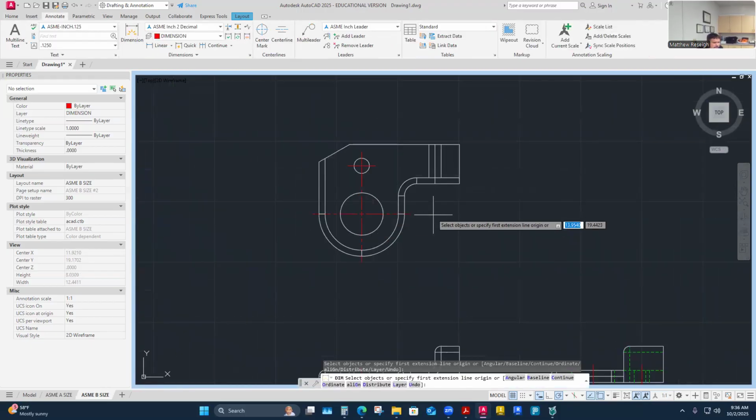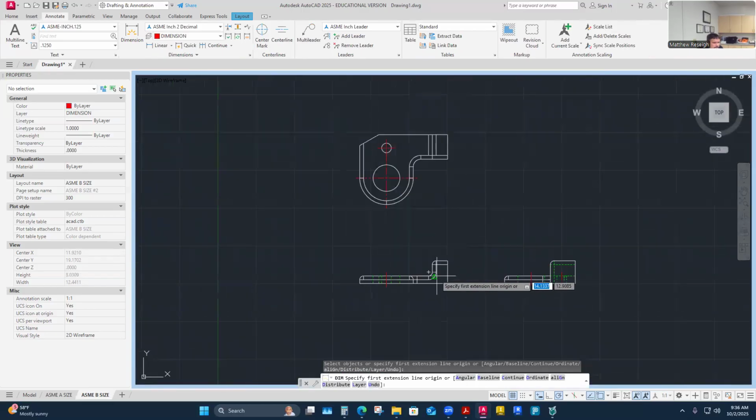So overalls. And really, I'm trying to get your heads working around like I'm going to have what I call these datums. I'm thinking of places where I'm pulling dimensions from, they're called datums, and I think of them as if I can kind of keep them to three, I'm doing good.